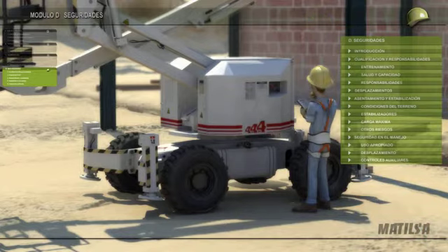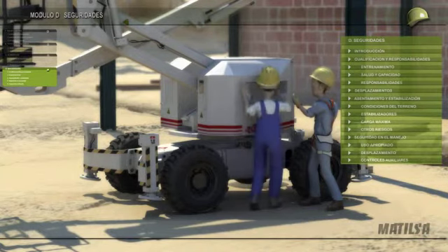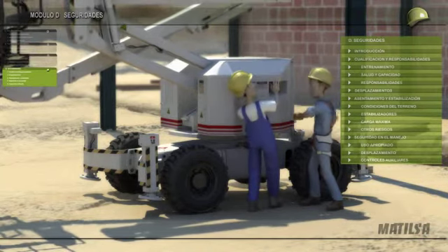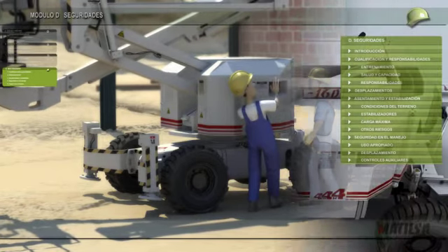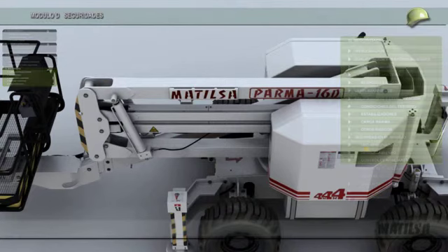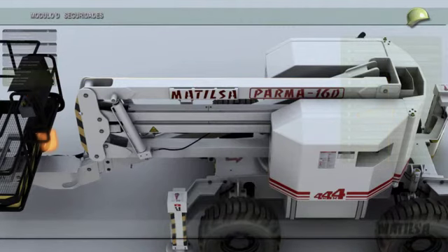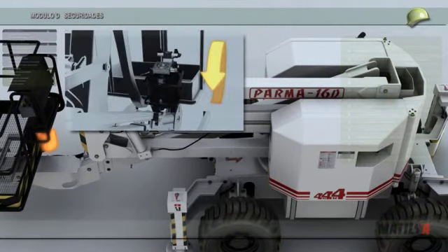Ideally, another worker would be in the work area who also knows the use of these emergency systems. To avoid these failing, you should not use them in the course of your normal activity with the machine. We could name the two systems to which the user has access: the stop by means of the emergency button located on the dashboard of controls, and the pump for the manual lowering in an emergency.